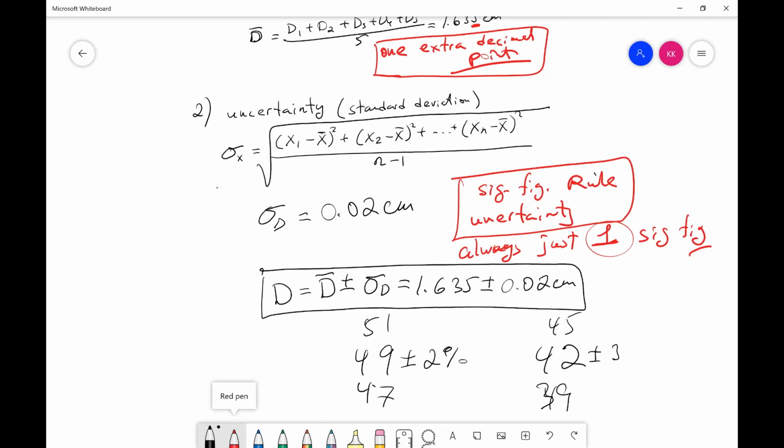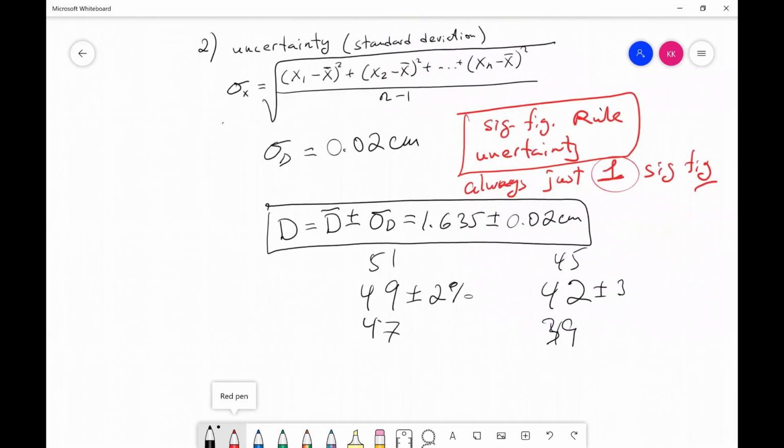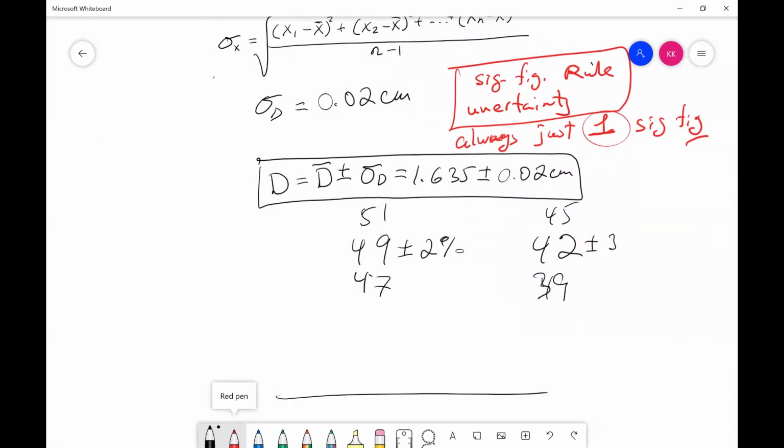That means anything that you measure comes with uncertainties. Same thing here. If you're talking about the diameter, what you're saying is this. Let's say this distribution is for my measurements, so my measurements spread out like this. The average represents the peak of your graph, but then you have plus uncertainty, maybe somewhere over here, or minus uncertainty, somewhere over there.